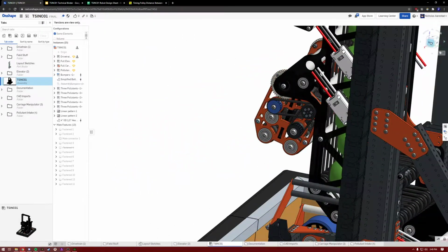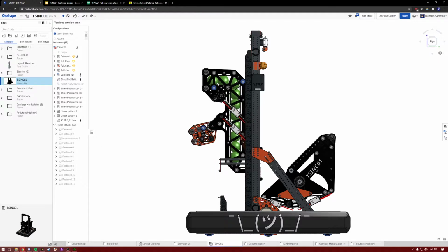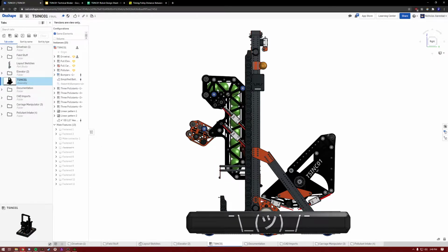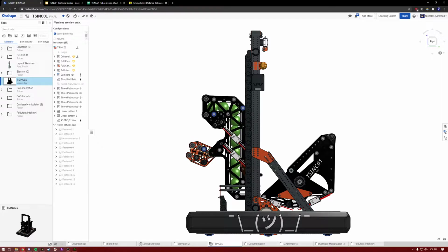In this lower position, this motion is apparently just kind of working. So basically, it's like this position, except all the way at the bottom, which puts this at about 18 inches and right at the edge of the bumper frame perimeter. That was a really intentional choice to make it super easy to grab from the loading stations with minimal movement. So this robot can operate for a lot of the match at its lowest position with a super low center of gravity, which is very intentional.